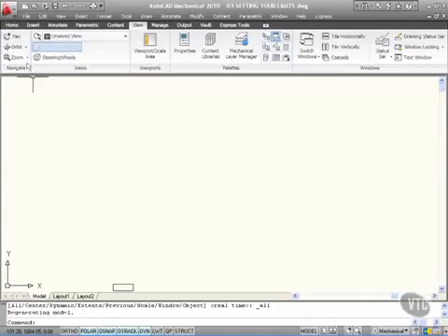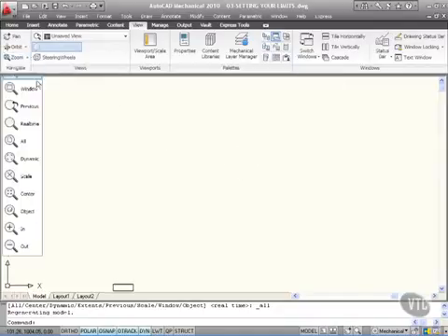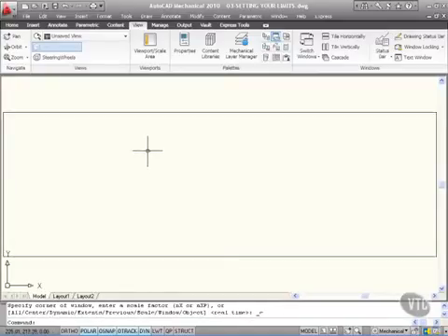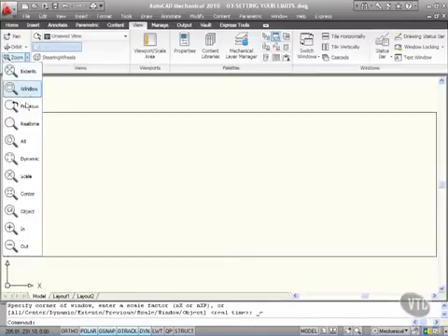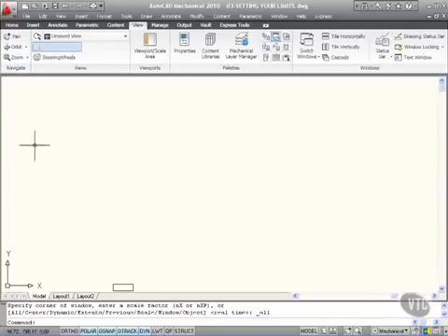So, Zoom Extent will zoom to the extents of an object drawn, regardless of its coordinates. Zoom All will zoom to the extent of your limits that you've specified by typing in those coordinates when you type the word limits and press enter.